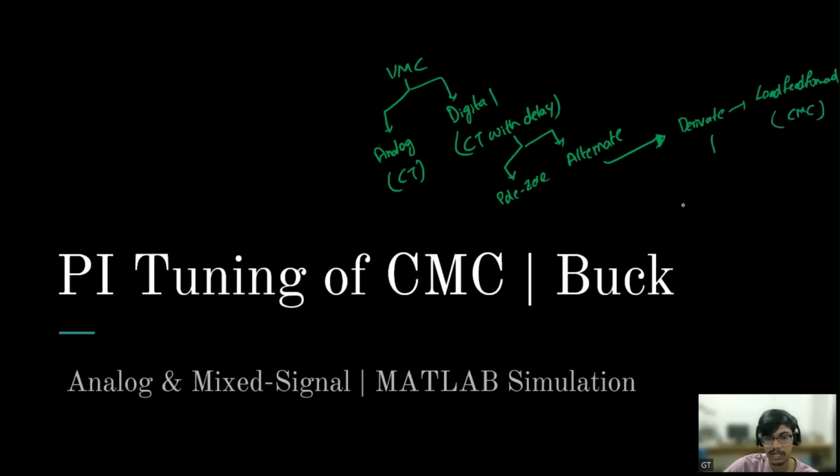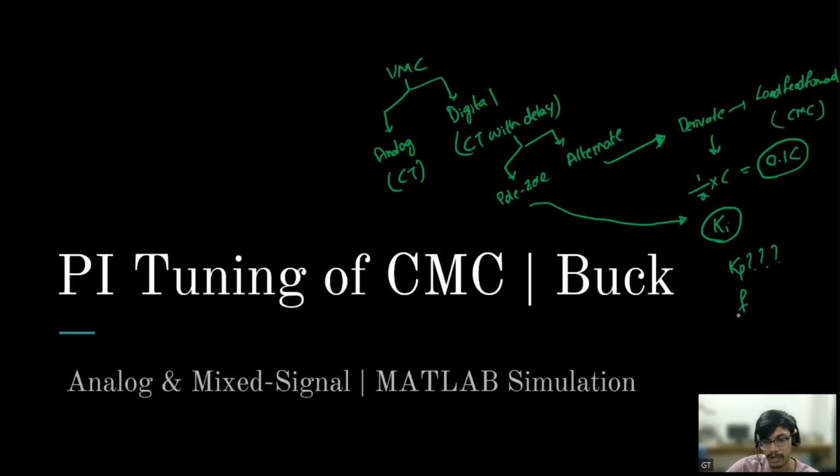From that expression for load feed forward in current mode control, we know that it should be a fraction of the capacitance. To start with, we have considered 0.1C, and Ki is whatever we are getting from pole zero cancellation, and Kp is chosen in such a way that the bandwidth omega c is 2 pi fSW by 10. So this is like a summary.